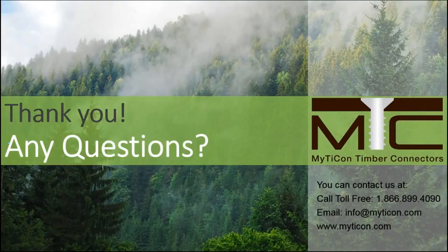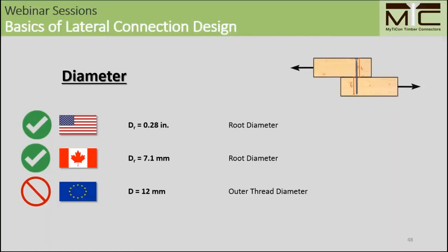Okay, yes, the diameter, I'll just quickly put up that slide. I said that here, that the diameter in US and Canada has to be used as the root diameter, and only in certain cases can we actually use the shank diameter of the screw.